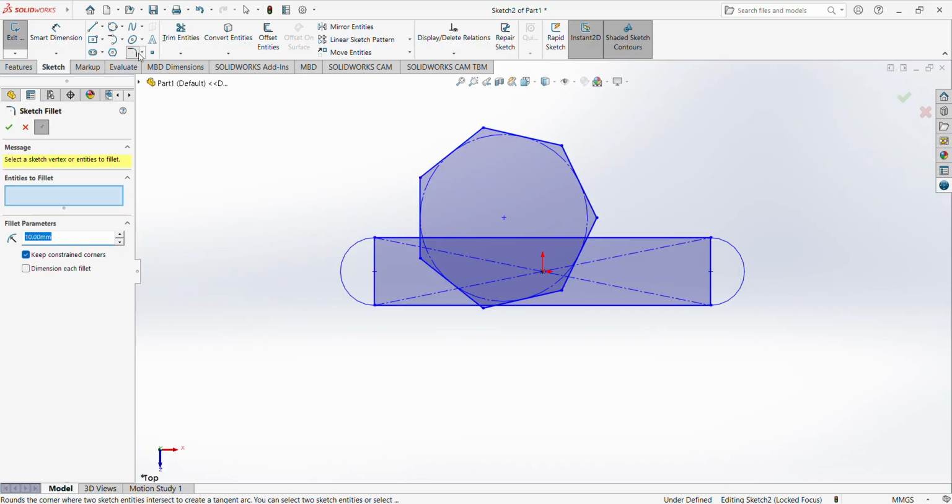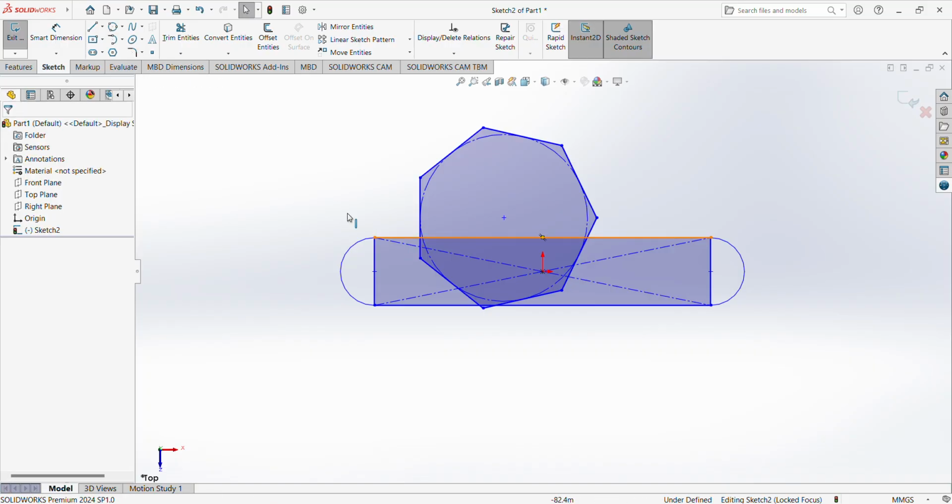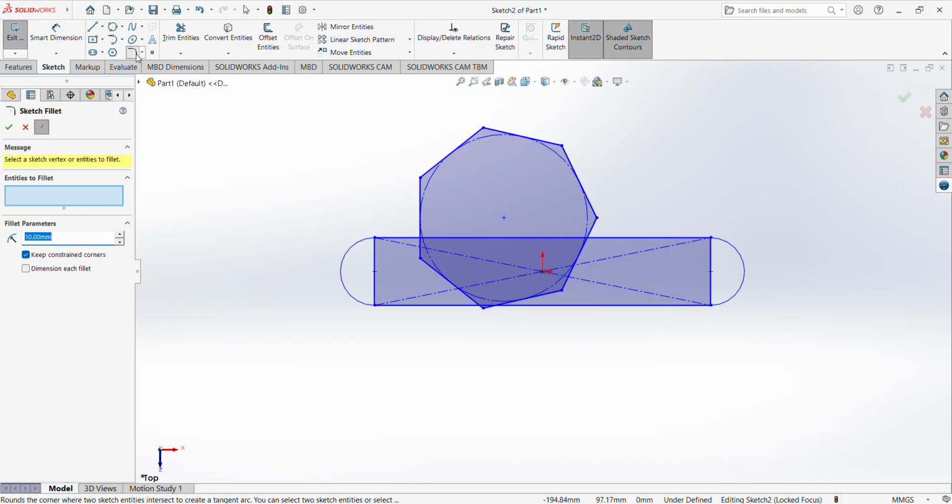Then the next thing we have is our fillet and chamfer tools. If you have watched any of my other videos, some of them already showed how to use the fillet and the chamfer tool. So basically you can start to do a fillet at the side of this rectangle. So let's try that. Fillet, just click the side you want to work with, that is here. So it's 10 meters from both sides. So you just click yes.